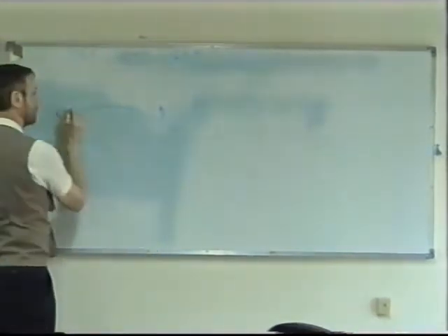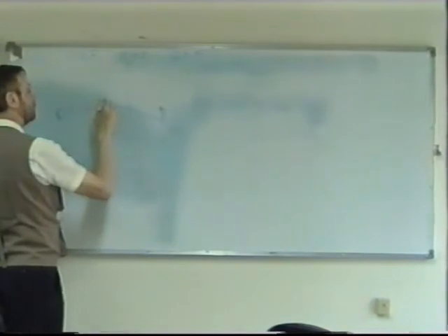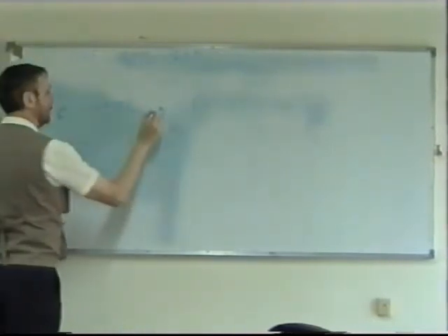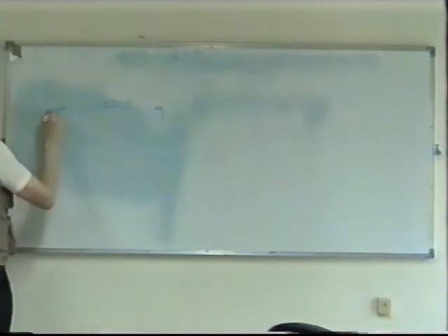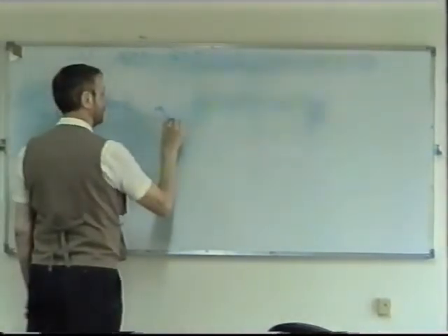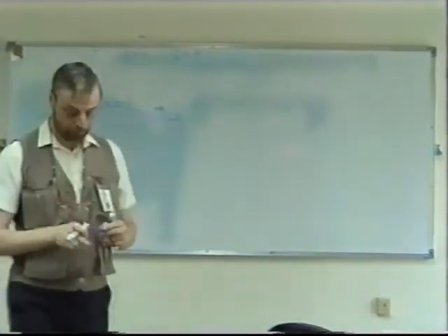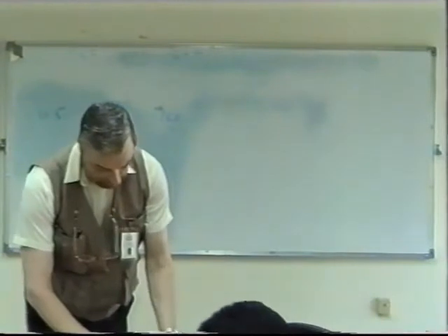Like that. This is supposed to be a straight line between them, which just touches the horizon. This is the maximum theoretical range, call that the range, of our signal. It doesn't matter which way we take it, either one can be the transmitter or the receiver. And if I say that this here is the TX height, TXH, and this one is the RX height, in meters, then we can derive a little formula, which I derived over the weekend, as to the maximum range.